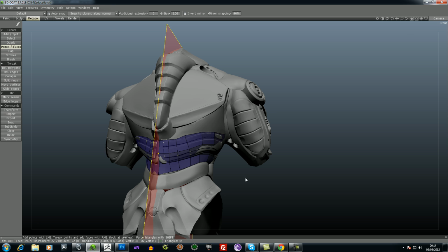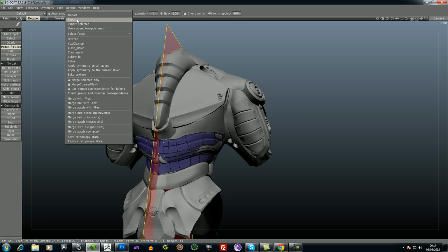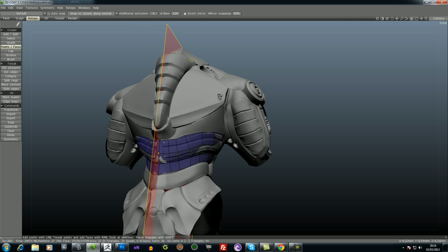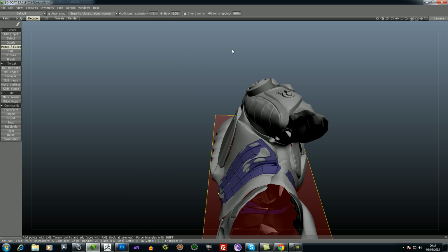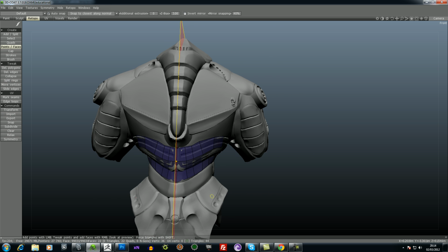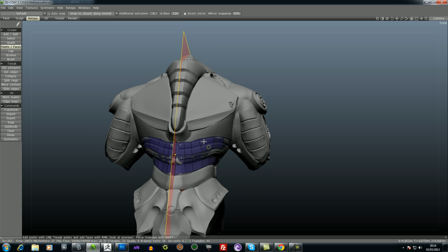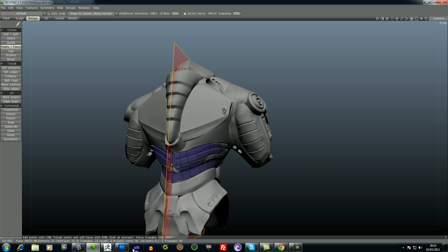And to get this new mesh out, I'm just going up to the retopo and exporting, but I will have to apply symmetry because I'm working with a symmetry plane. So once that is done, then I would use xNormal, and this process I'm not sure about. I know that you'll have this low poly version and your high poly decimated version. You do something in xNormal and you get a lovely normal map from it.